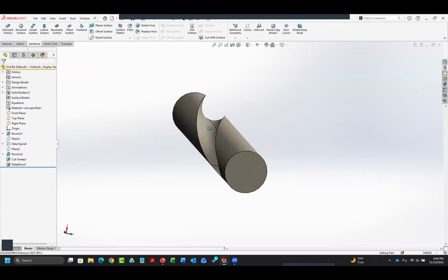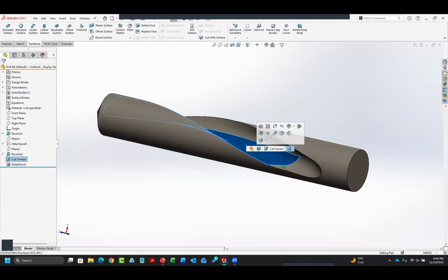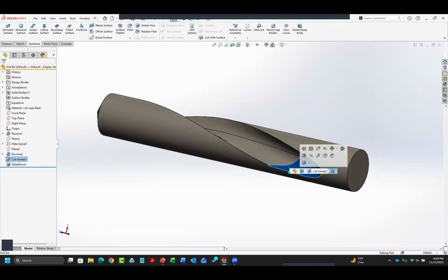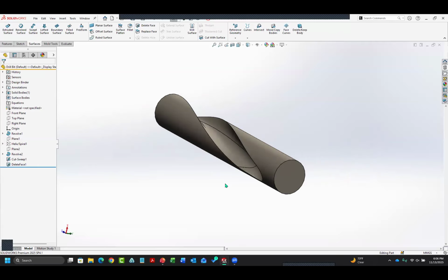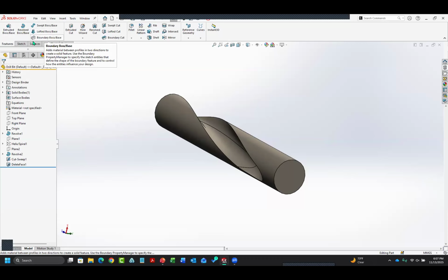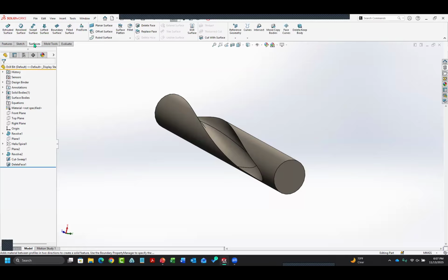Now, a couple other things I want to do is recreate essentially these three surfaces, but as one surface. I'm going to use some of the existing geometry that's here to set up my sketches so that I can eventually use a boundary surface. If you notice in your surfacing tools, there's an extrusion, a revolve, a sweep, a loft, and a boundary. They work identically to their counterpart features in the features tab, other than we can sometimes use open sketches where you can't do that in the features tab.